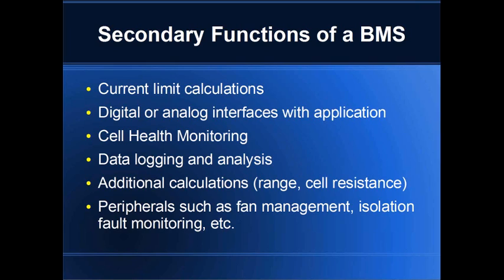Some battery management systems will also provide health monitoring. They monitor each individual cell, and if there's an issue, it can tell you what's going on with the battery pack. This is generally a little bit more helpful for larger format battery packs, like in a vehicle or energy storage application where you might go in and replace a cell. In a lot of consumer devices, you may just want to know that the battery pack is bad and it needs to be replaced as a whole. It may not make sense to go in there for little cells and replace cells.